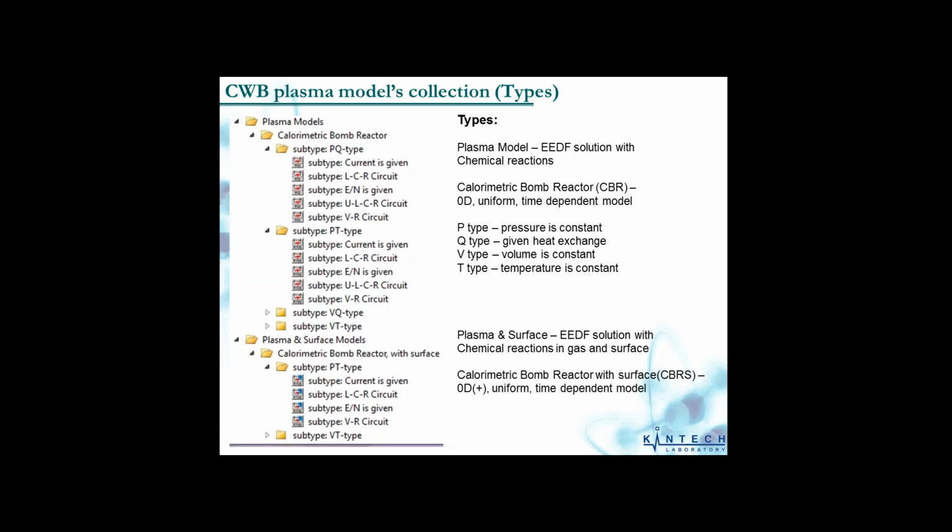So there is a possibility to take into account diffusion of the species from the gas to the surface, reaction between them, reaction between the surface species on the surface, or moreover, reaction between the surface species and the bulk species. It is a very useful tool for simulation, for example, of layer deposition.